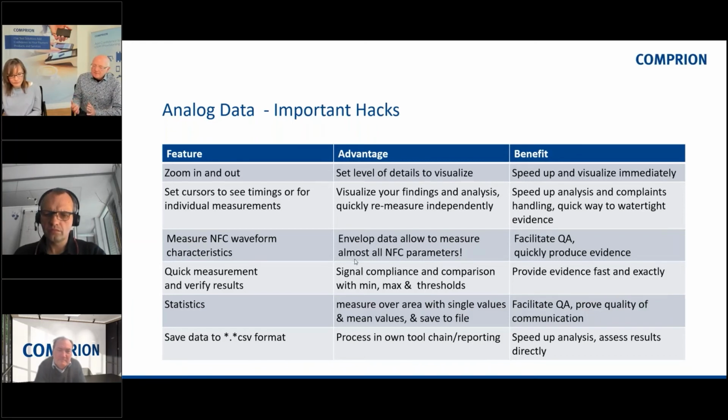And in most cases we are receiving logs from customers to analyze them. Then we can see that the positioning of the antenna is a very important factor, especially the positioning between the antenna and the PICC. Yes, because of the load modulation, we have to see every exact load modulation. And in case we are missing, for example, a PICC response, then of course we have incomplete APDUs, and we make these incomplete APDUs visible as an unknown APDU.